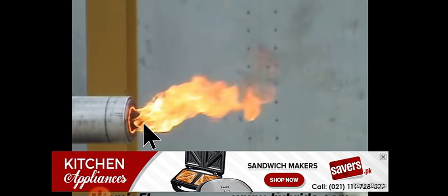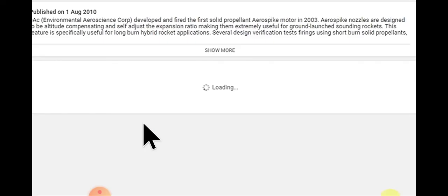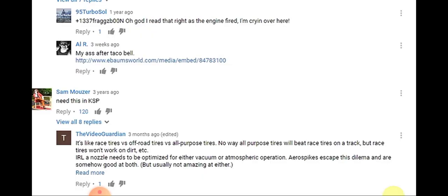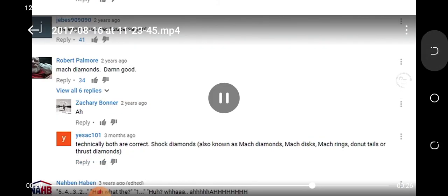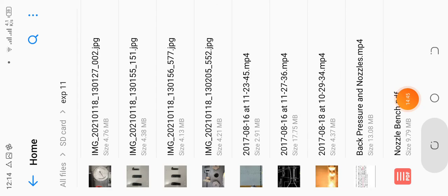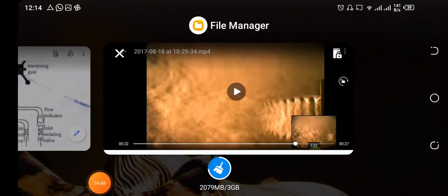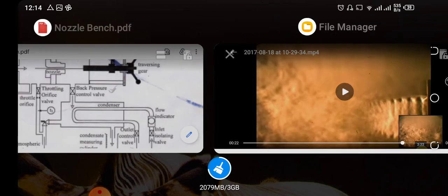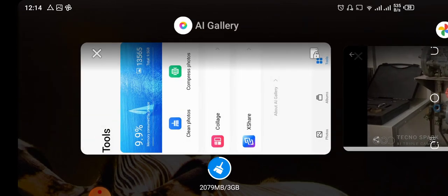We also don't want a very large expansion fan, because it reduces the velocity and decreases the efficiency of the nozzle. So the ideal condition after discharging the fluid is to have the same pressure as atmospheric pressure.